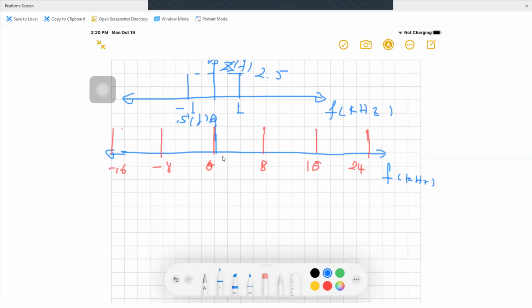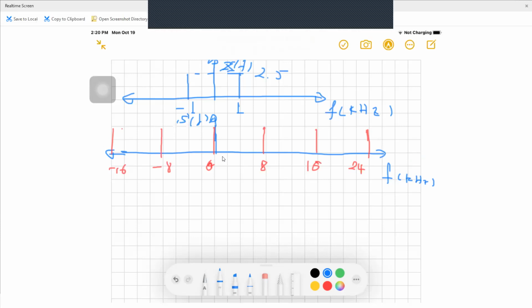So it depends on the requirement. At the beginning, I told you how we determine the sampling rate. It's a good question, thank you. In this example, we selected the sampling frequency greater than the Nyquist rate: 8 is greater than 2.